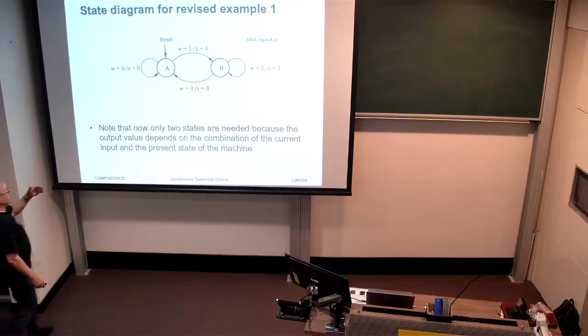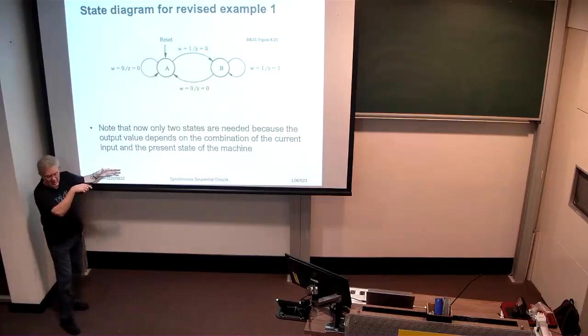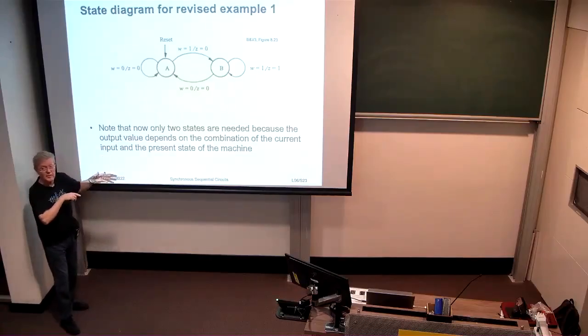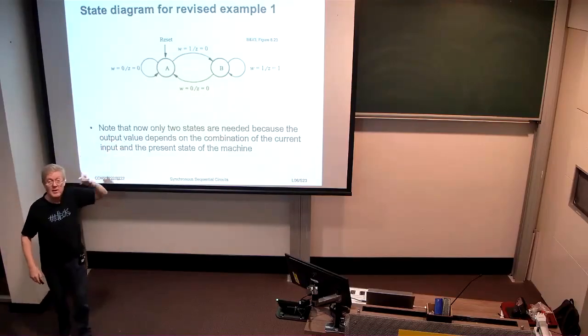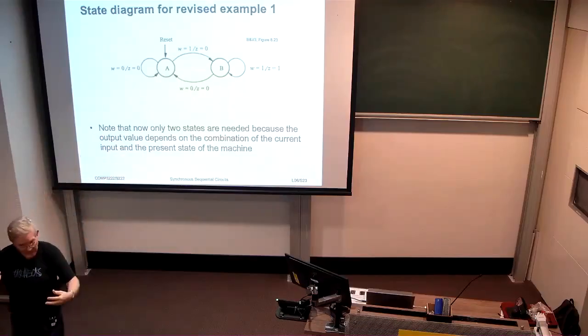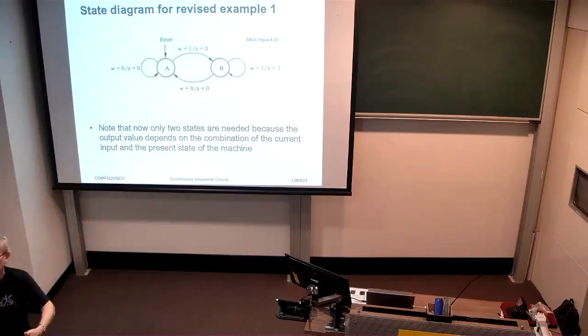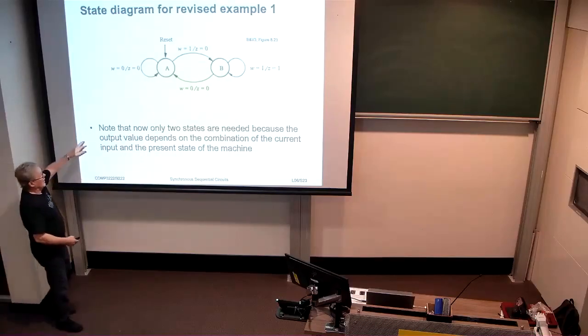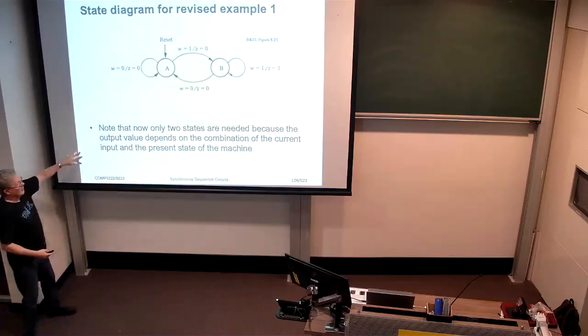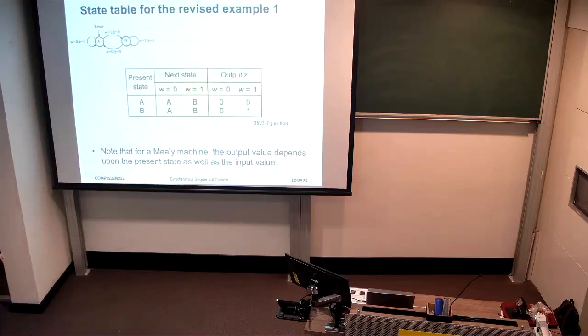Okay. So the static power will go down. The dynamic power doesn't necessarily go down, but with 1 flip-flop versus 2, the dynamic power, the power that is consumed when the system changes state, has to go down because you're only changing state for half as many state variables as you would have been doing previously, right? So power is definitely less with this guy as well. Right. Only got 2 states, therefore only 1 state variable is required.